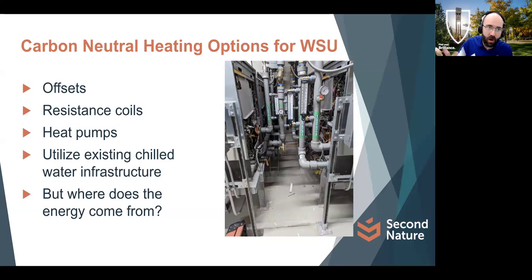These are all water source heat pumps, and we've connected them to our existing chilled water infrastructure. The chilled water loop that our central plant uses is circulating water 24/7. That's the energy source for these heat pumps. As these heat pumps inject heat into the space or remove heat from the space, the temperature of the central loop is going to change.